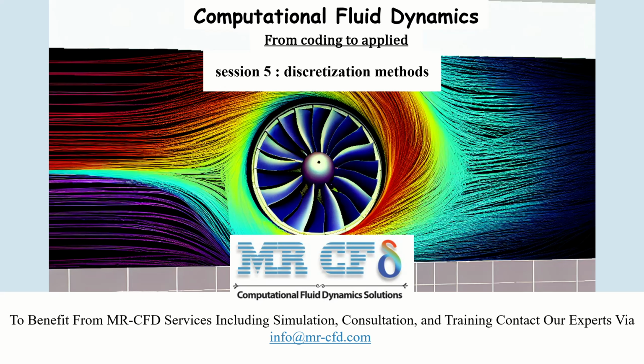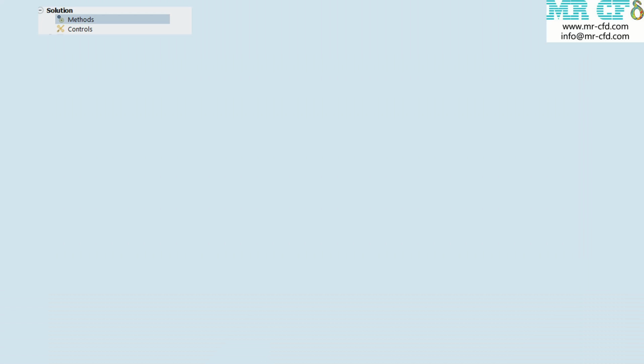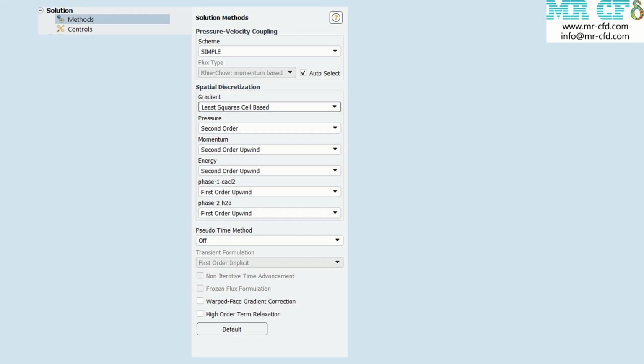In this video, we will explore different types of discretization schemes that Fluent uses. In the Solution section, under the Methods tab, after selecting the pressure and velocity coupling method, you can choose different discretization schemes for each variable. Let's explain them one by one.